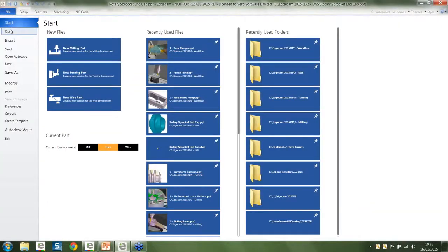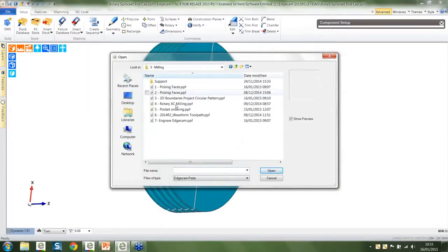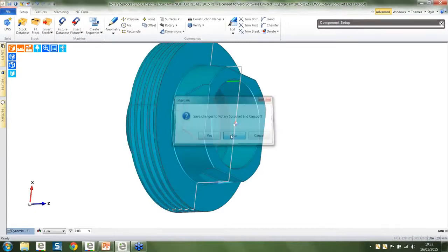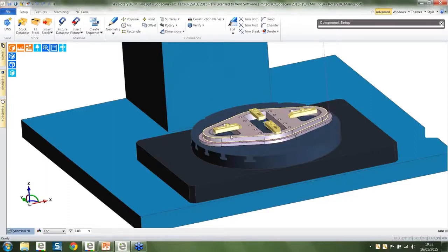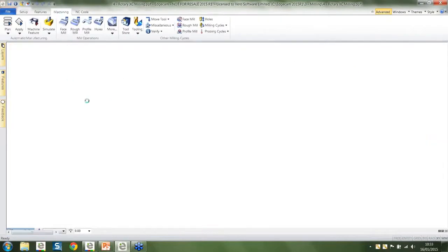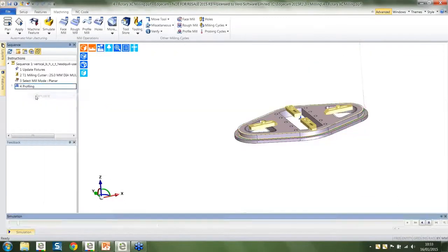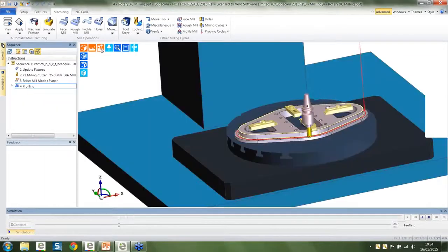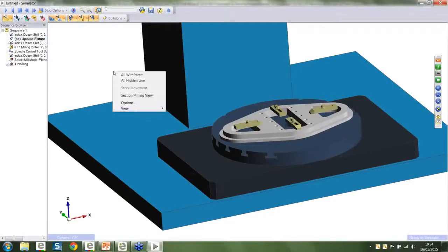Let's just open up an item here, move back onto number 3, and we'll start with maybe one of the simpler ones. This item is to do with, as I said before, milling, and the movement as we machine around the part. What we see here in plain Edgecam is just a profiling cycle. As we move that inside the machine simulator, you may guess what's going to happen: we're going to go over axis and cause over travel.